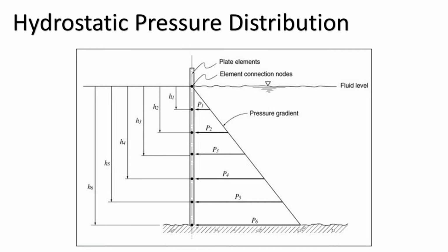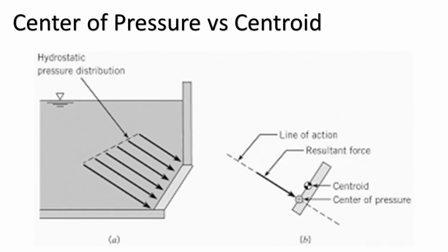According to the hydrostatic equation, the magnitude of hydrostatic pressure P increases as the elevation Z in the fluid decreases. When hydrostatic conditions prevail, any panel that is not horizontal is subjected to a hydrostatic pressure distribution. A pressure force acts at a point called the center of pressure, which is calculated so that the torque due to the pressure force is exactly the same as the torque due to the pressure distribution. In other words, if you want to replace the pressure distribution with a statically equivalent force that acts at a point, the correct point is the center of pressure.